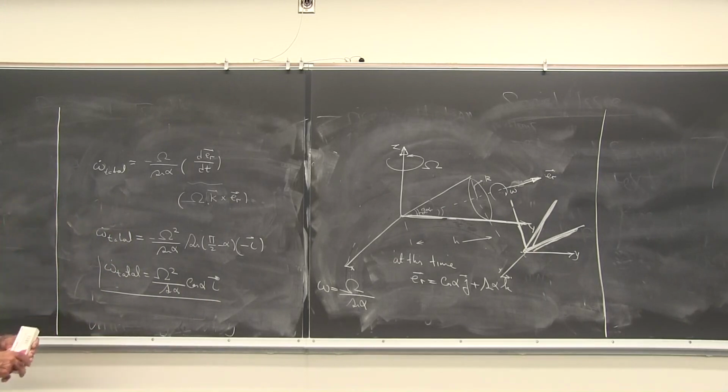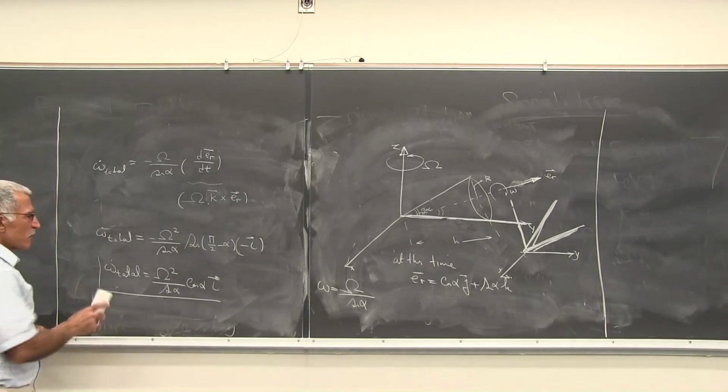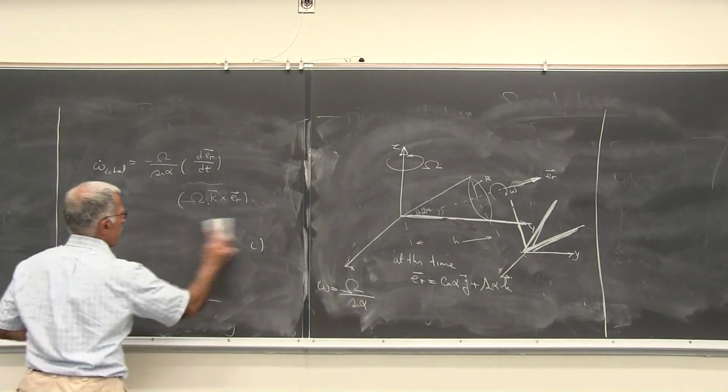It is very important to understand in instantaneous axis of rotation that you have to identify, although all of the rotation is the same, you identify one particular line that has all zero velocity. And once you identify that one, you may proceed. There are other ways to solve this problem, to find the small omega, but we leave it for the next problem that I'm going to solve for you.